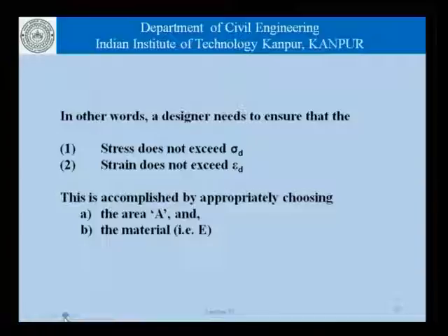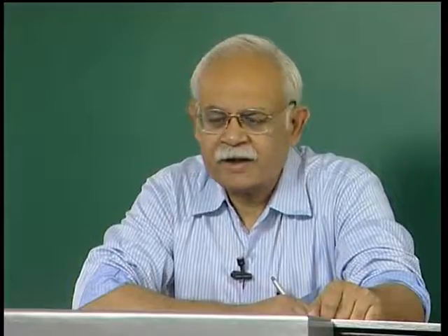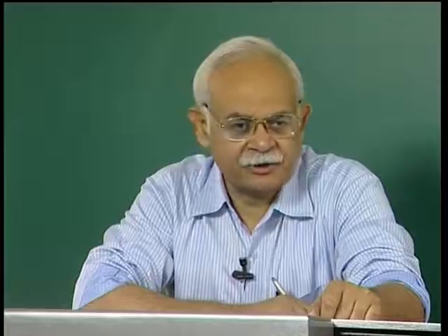So basically, analysis is the exercise which tells us the response of the structure to a given load when the material properties and the geometry of the member is known, and design is the exercise where the geometry and the material properties of the member are determined for the same load with the specification that the response is acceptable. Surely there will be a response, surely there will be some deformation. Now, whether that deformation or that response is within acceptable limits, that is what is the design exercise.